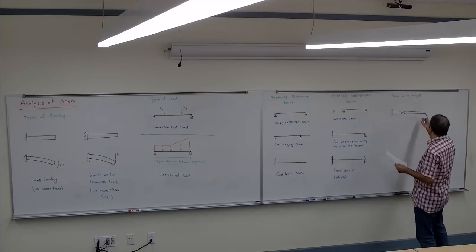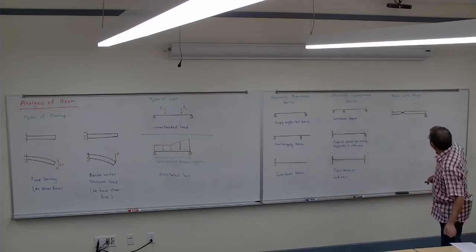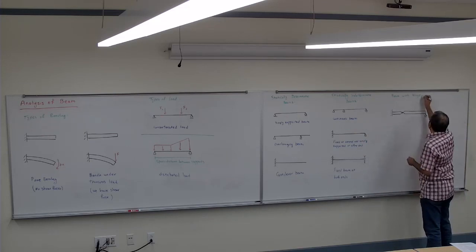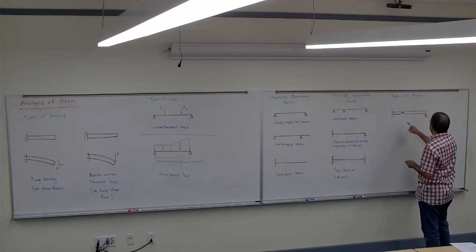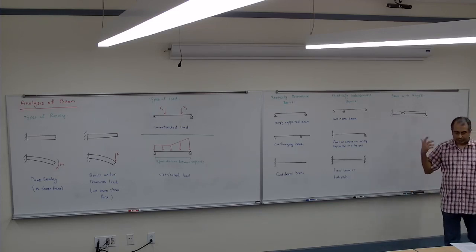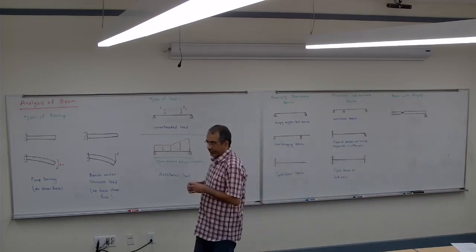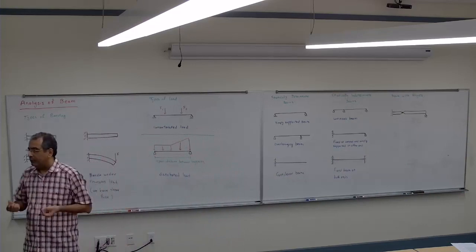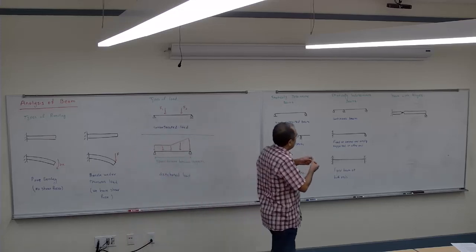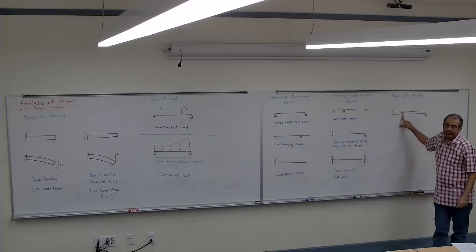So if you look at it, at first glance, it can have 1 hinge or more than 1 hinge. So I have 3 unknowns here, 1 unknown here. I have 4 unknowns in total in that beam. So with statics, I cannot do anything with that. But I have a hinge, and in the hinge, the beam can rotate. Nothing prevents the beam from rotating about that hinge.